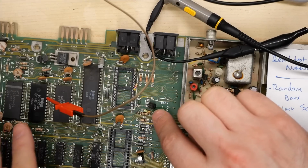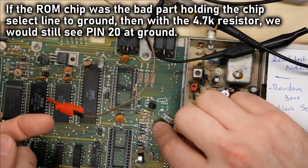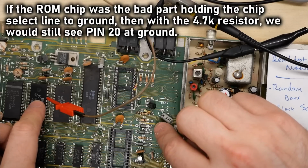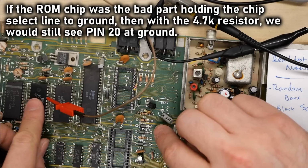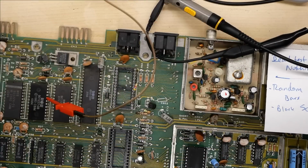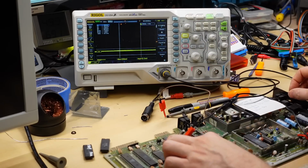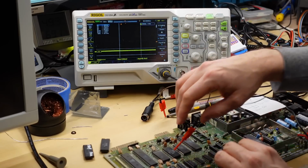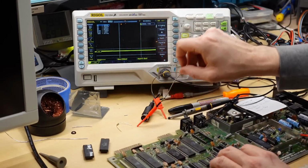So if everything is working correctly with the ROM chip, it should just pull the kernel ROM permanently high to 5 volts on this pin. Remember, this was a pin that we never saw really coming off of ground. It was only coming up a little bit. So let's turn this on and check out the oscilloscope. And there it is. It pulled it right up to 5 volts, which means that I don't think there's anything wrong at all with the kernel ROM, and I think everything that was going wrong was the PLA.